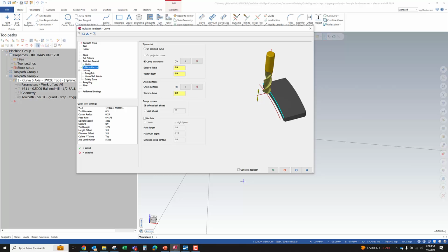And the dream is to be able to just program directly off a 3D solid model and not have to create any extra geometry. I've seen times where that worked successfully, but more often than not, I end up having to create additional geometry to give me the control I need.